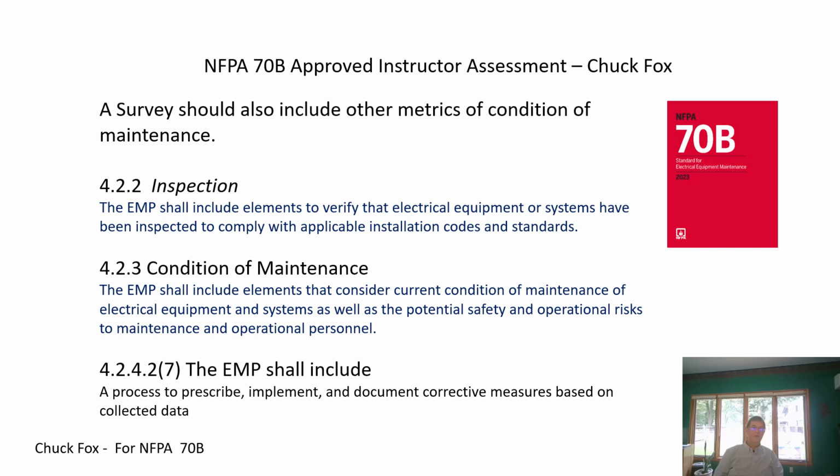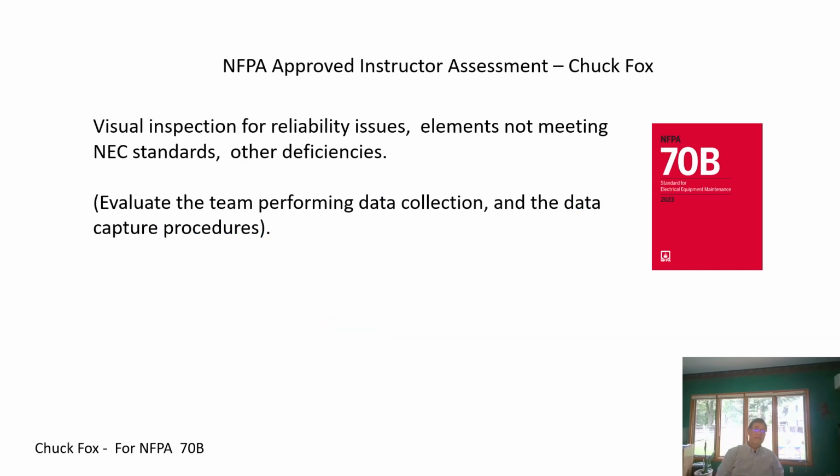And again, in review, the other additional component for the electrical maintenance program would be its entire problem reporting, corrective action, and definition process of how various anomalies within the electrical system shall be documented. The tasking done to achieve these broader requirements beyond infrared thermography would be visual inspections looking for reliability issues, elements not meeting NEC standards, and other deficiencies.